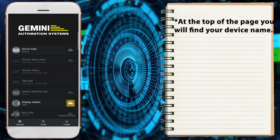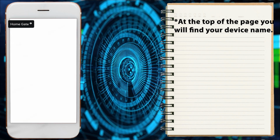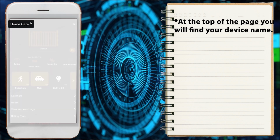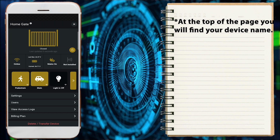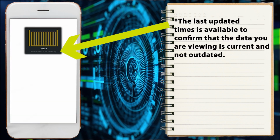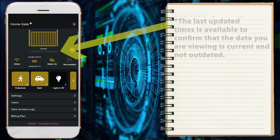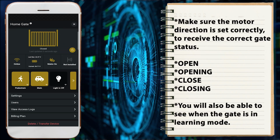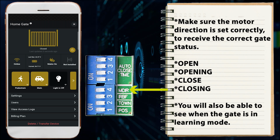At the top of the page, you will see the name of your device, accompanied by a gear icon. This icon provides access to the device's settings. Below this, a visual representation of a gate, and it will show its current position. Please note, if the motor direction is set incorrectly, the gate's displayed position may appear reversed. To correct this, adjust the motor direction on your PC board accordingly.